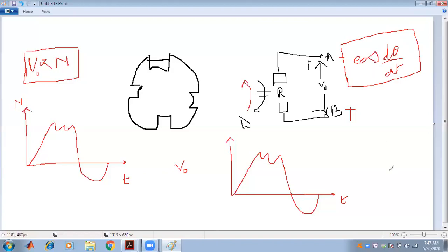And again, the speed of that particular motor, or any object which is connected to the shaft of the rotor of the DC generator, has to be measured with the help of the tachometer or the DC tachogenerator, and the speed is directly proportional to the voltage that is induced in the tachogenerator.